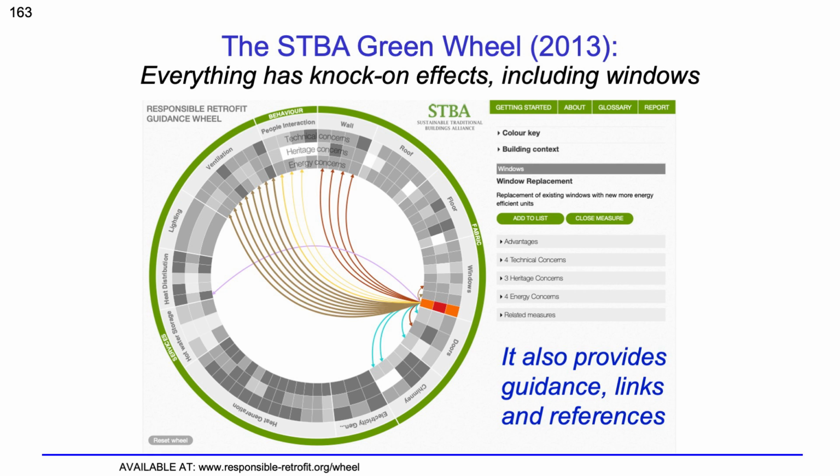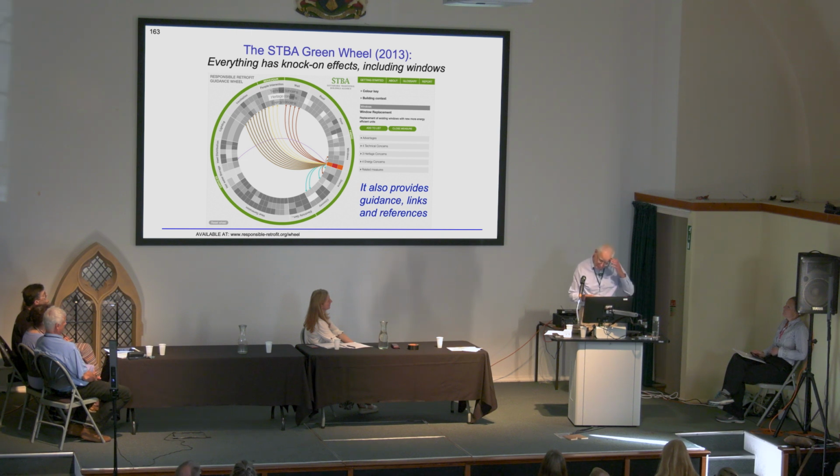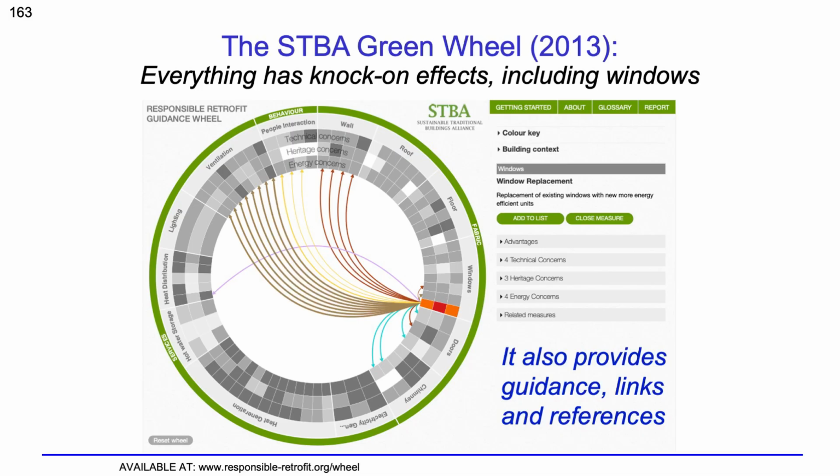And then that started interacting with, well, if your window's really well insulated and draft proof, then your relative humidity might go up, and then you might get condensation problems somewhere else. You might get that mold. Also, your surface temperature differences between your reveal and your window might become more extreme, and your reveal might start getting into a problem. And then also, ventilation needs to be taken account of over here. And also, there's another thing, heat generation. If you reduce the heat loss from your windows, you may not need to replace the boiler with as big a heat pump as you think you need or whatever. And it goes across to other things. How does it relate to chimney ventilation? Chimney ventilation might be quite useful if you've sealed your window up a bit, or maybe it wouldn't be.